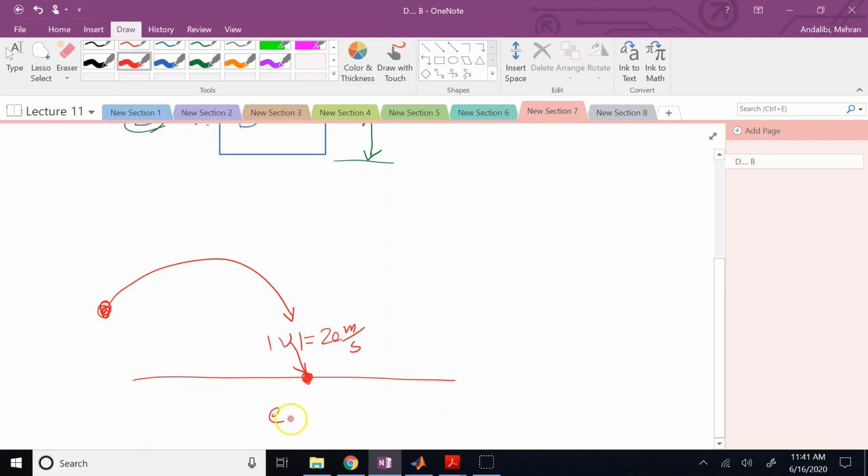So do I use a constant E for this impact versus the next one? Well, we know the next one is not going to happen with the same V, right? Because I lost a little bit of V here because of impact. There is some deformation, permanent deformation. And then the drag reduced the velocity. So the next one might happen with 16 meters per second.